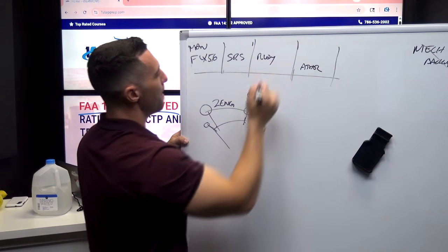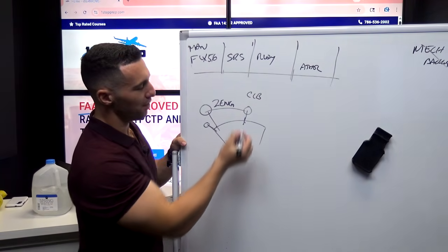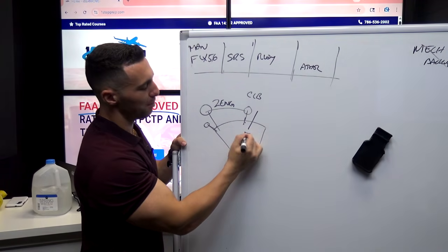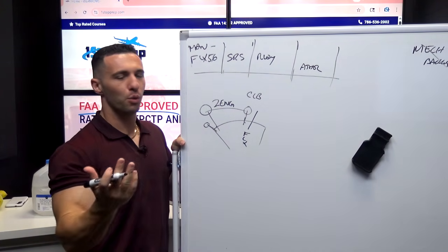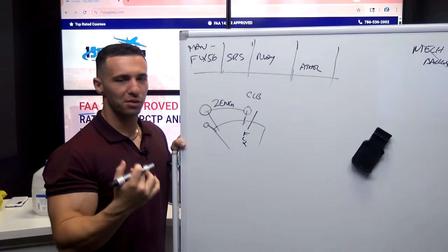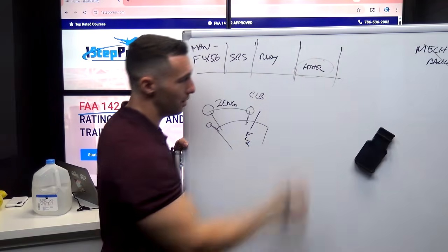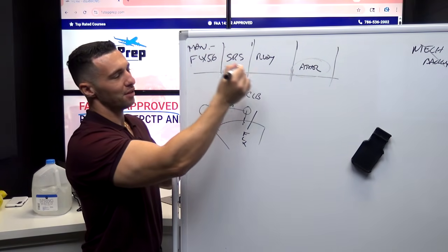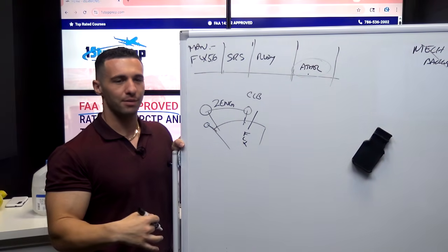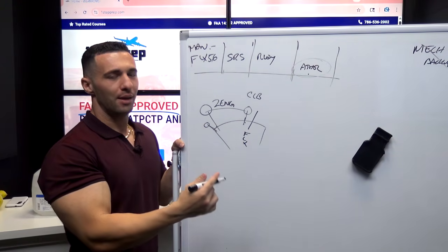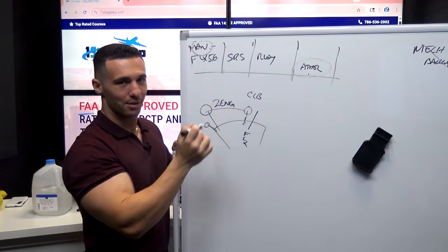So the MAN FLEX is what? Manual flex. What it really means is the thrust lever is here in the flex position, which is very much a manual position. The auto thrust has no authority, no jurisdiction. It's not going to reduce the thrust for you, which is why, by the way, auto thrust is blue. The reason it's blue is because it's armed, it's not active, which would have made it white. And the reason it's not active is because it's out of the active range, which is why it reads manual.